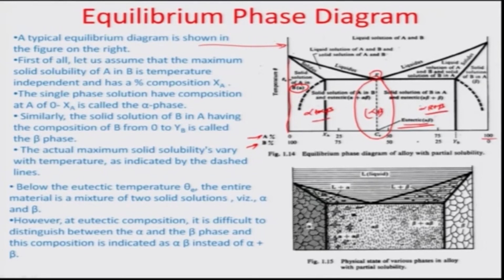So, in a similar manner to the ice system, we are trying to generate information from this. Okay. So, you can think of it that this is the indistinguishable phase, the eutectic phase, this is the hypereutectic phase, and this is the hypoeutectic phase, comprising of beta plus alpha beta and alpha plus alpha beta respectively. So, these are the phases where you have complete solid solutions of alpha structure or complete solid solutions of beta structure.